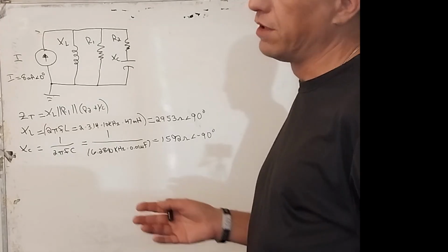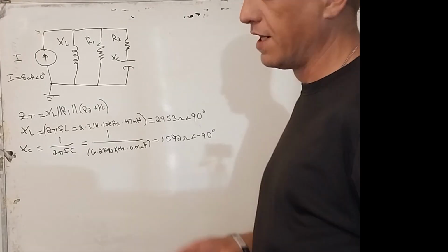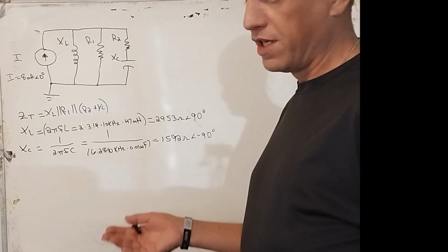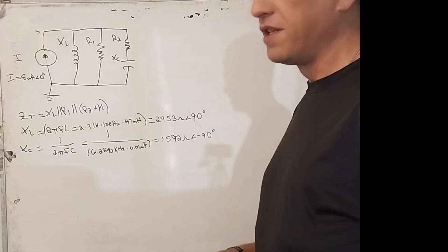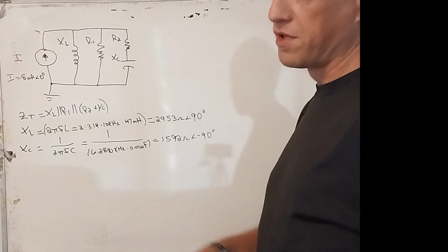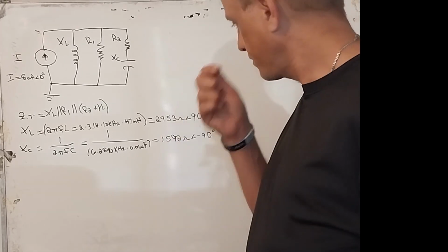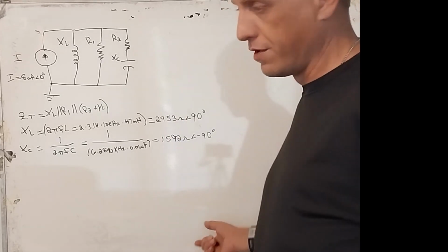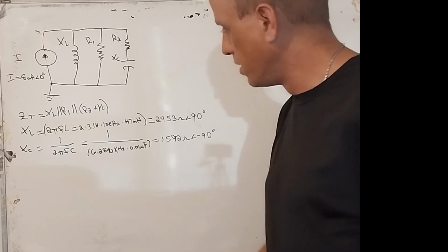But without rectification, we can do AC analysis. But it's easier to use a function generator because I can just supply how much voltage there is, so it's much safer. And I can use an oscilloscope to measure the waveforms as well.